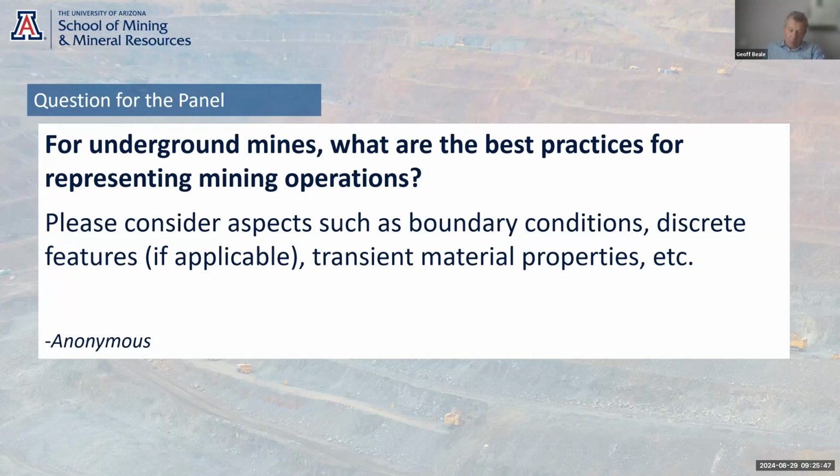There's one mine, a 1,500-meter deep mine that I've worked at for many, many years, and 20 odd years ago, we got to the point where we were having full hydrostatic conditions 1,500 meters below surface. So we're looking at 150 bar ahead of tunnels, purely because it was connecting to the surface through old exploration drill holes.